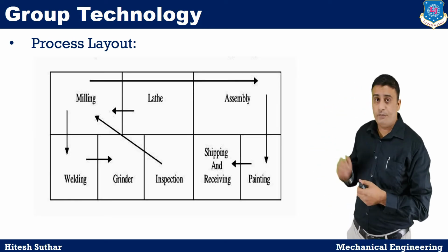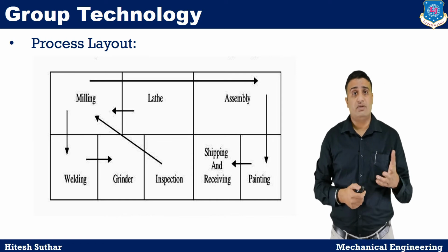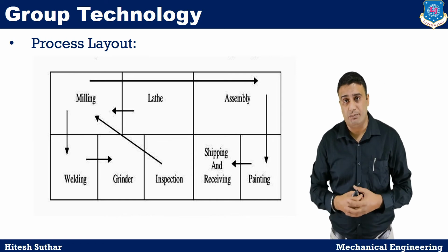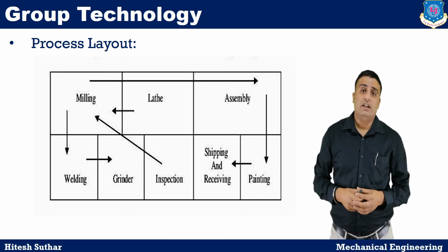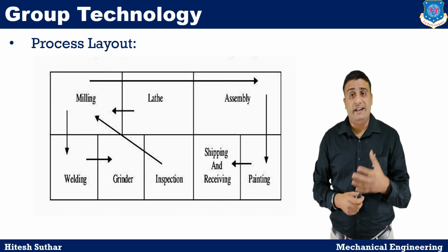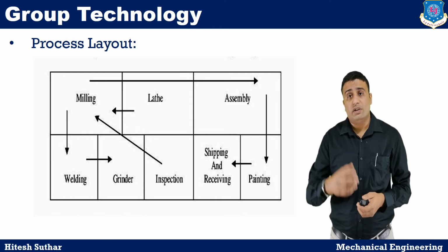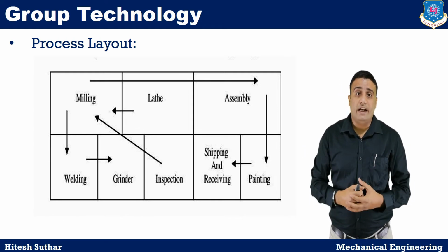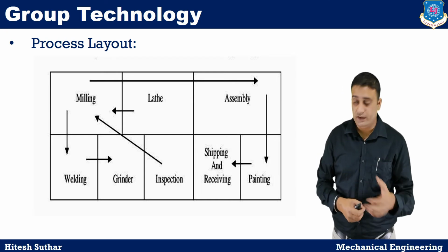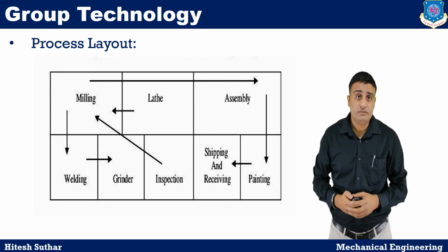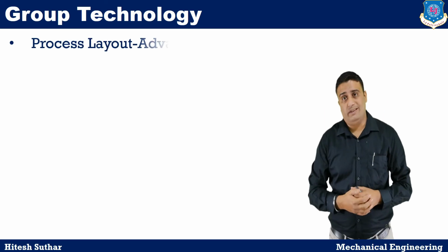As you see in the figure, a manufacturing example would be a machine shop. A machine shop generally has separate departments where general purpose machines are grouped together by function, for example milling, grinding, drilling, hydraulic presses and lathes. Therefore, facilities configured according to the individual functions or processes have a process layout, as shown in the figure. Now let's discuss the advantages and disadvantages of the process layout.